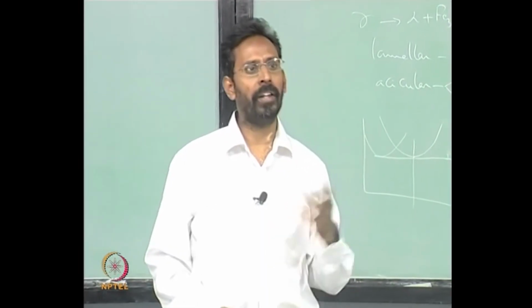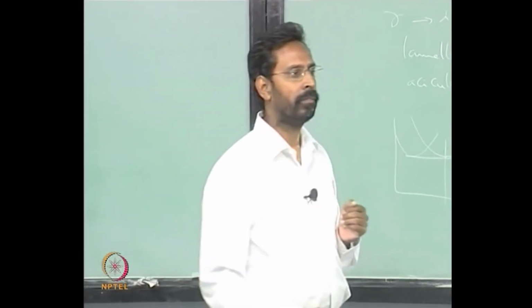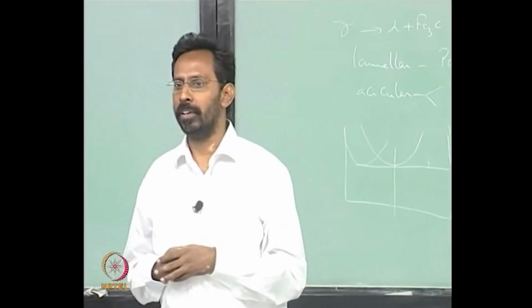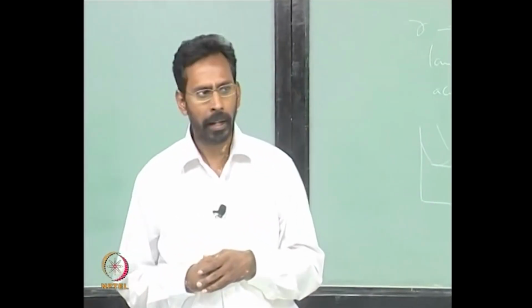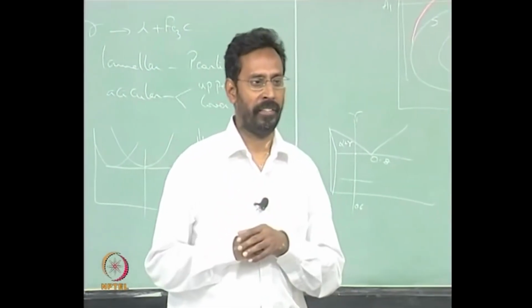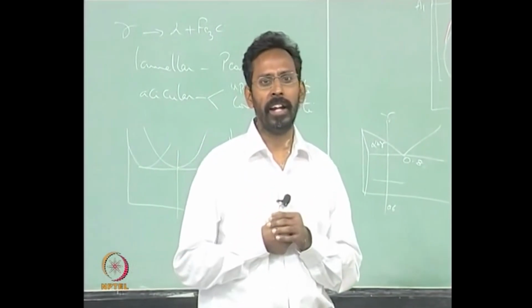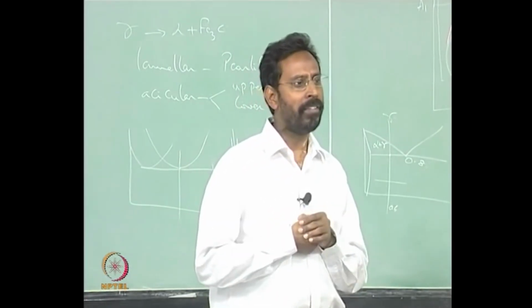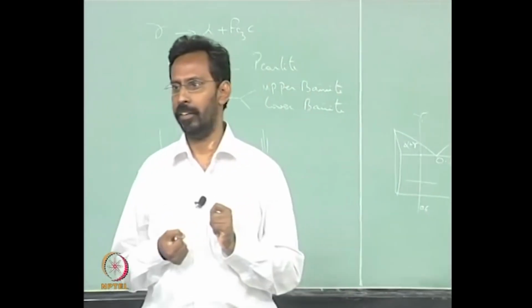Normalized sample. Anything more? The interlamellar spacing in the pearlite is coarser in the annealed sample and it is finer in the normalized sample. Why? Because the nucleation rate is higher. Why is the nucleation rate higher in a normalized steel?